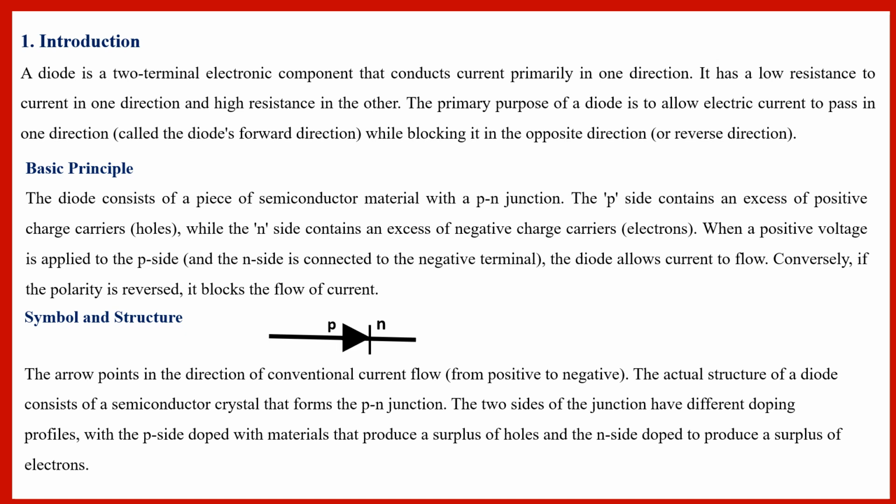You may see the picture of the PN junction diode, which is being shown in this particular figure. So this is the PN junction diode. This is the P side, which is represented as an arrowhead, and the line, which is the N side. So P is positively connected for the forward biasing, and N is negatively connected. This arrow basically points in the direction of conventional current, which flows from positive to negative side.